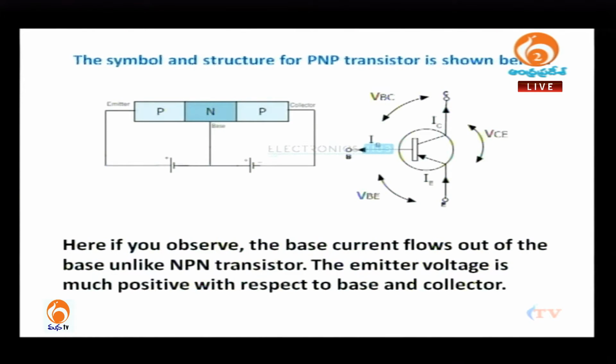The reverse bias applied across the collector and base junction will sweep these holes towards the collector region. During the short stay in which recombination takes place, some of the holes are lost in the base region. The transistor is considered to be good if fewer recombinations take place in the base region.